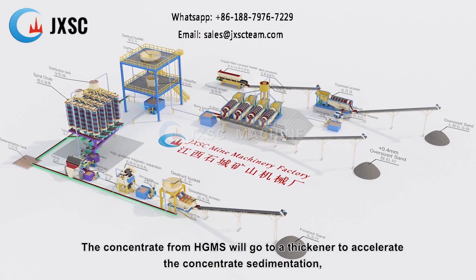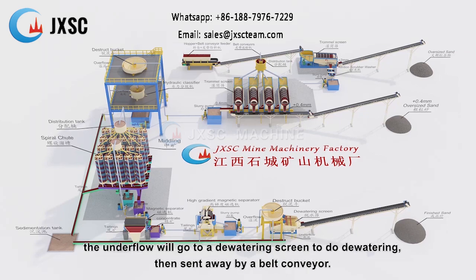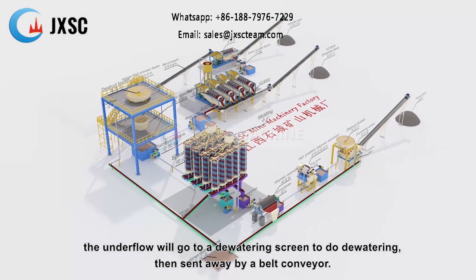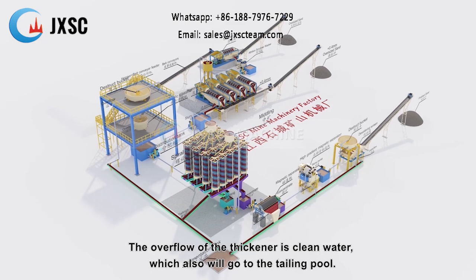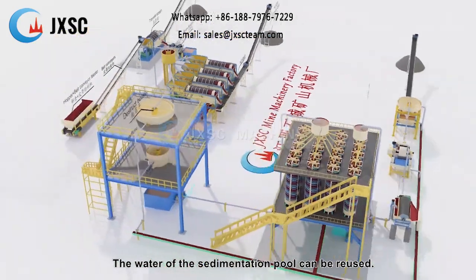The concentrate from HGMS will go to a thickener to accelerate the concentrate sedimentation. The underflow will go to a dewatering screen to do dewatering, then sent away by a belt conveyor. The overflow of the thickener is clean water, which also will go to the tailing pool. The water of the sedimentation pool can be reused.